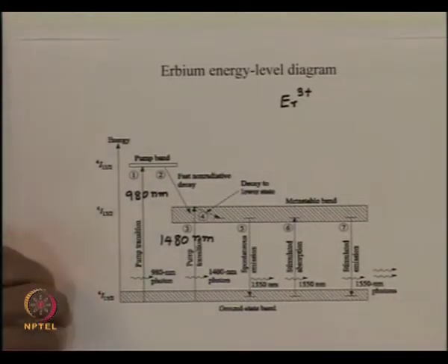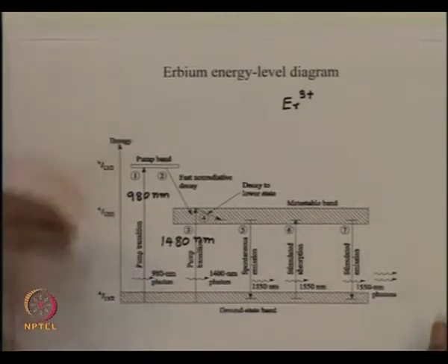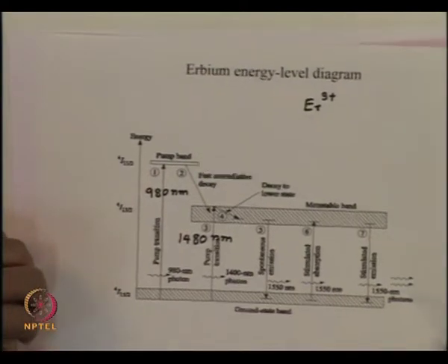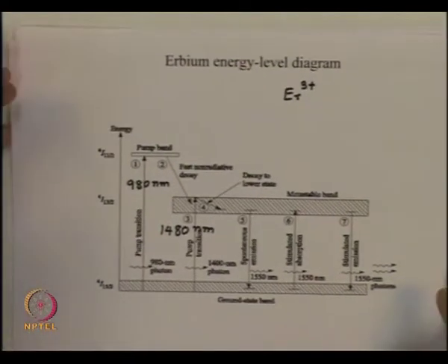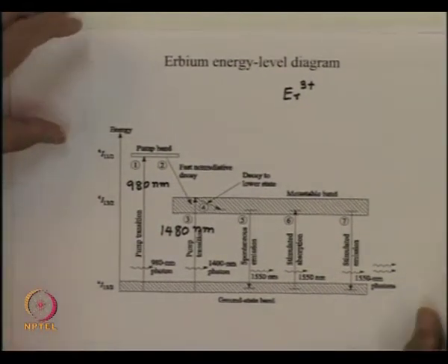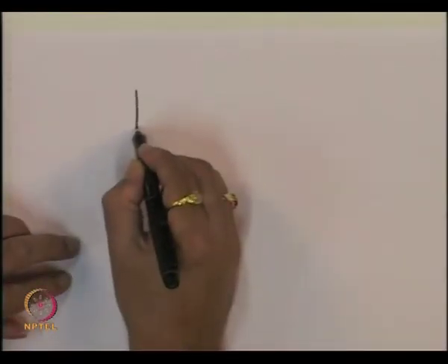If you take very low optical powers, minus 50-60 dBm, the gain is rather large, but as the optical power increases, the gain starts dropping. So the typical characteristic of optical amplifier gain will look like this.